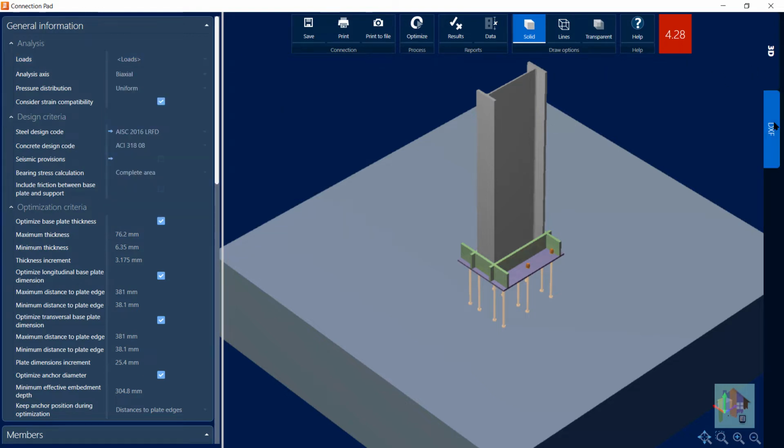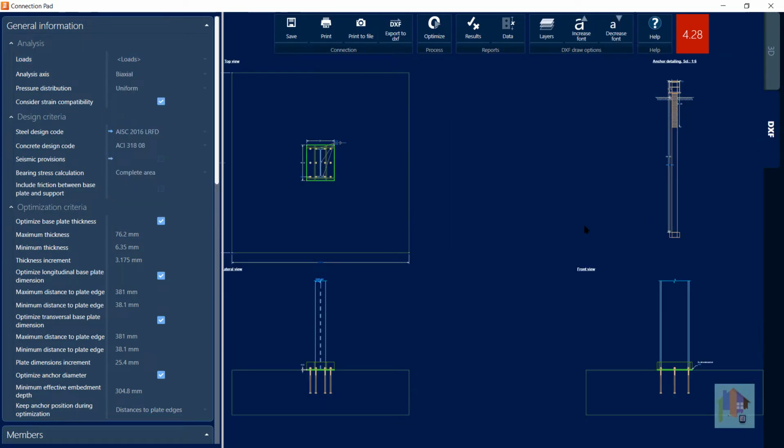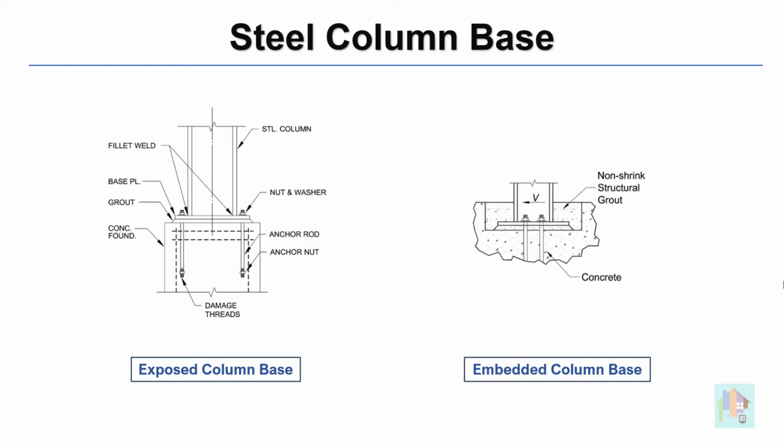Before going into the details, I want to discuss few basics, how the steel columns are connected to the foundation or pedestal and how the force is transferred from the column to the soil. I have briefly discussed about the support assignment in part 1.1. For any PEB structure, column base can be exposed or embedded within the concrete, but the columns are not directly connected with the foundation. There are few additional structural components which take part in the force transfer.